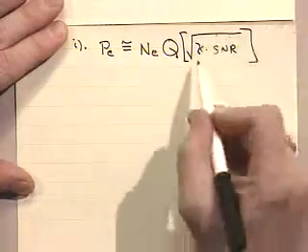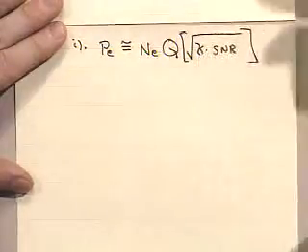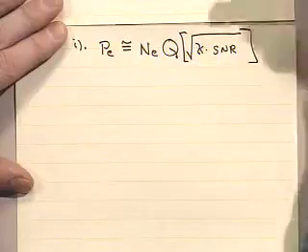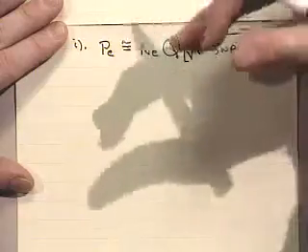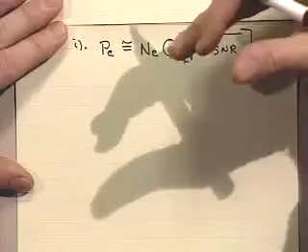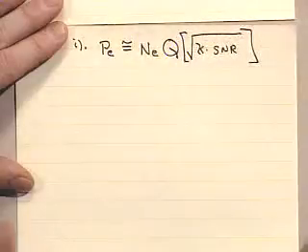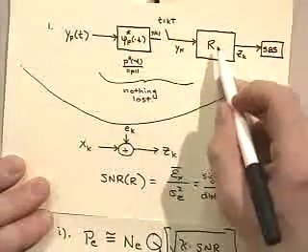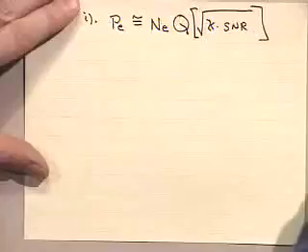And that is going to be independent of the actual signal constellation. If I know whether it's QAM or PAM, complex or real, different number of points in the constellation, so what? If I've maximized the signal-to-noise ratio for any of those types of constellations, I will have the lowest probability of error in my receiver. So one of the things I'm going to try to do here with R is to set up its structure within certain limits of complexity so that I maximize the signal-to-noise ratio. If I do that, I'm going to say I've done a good job.